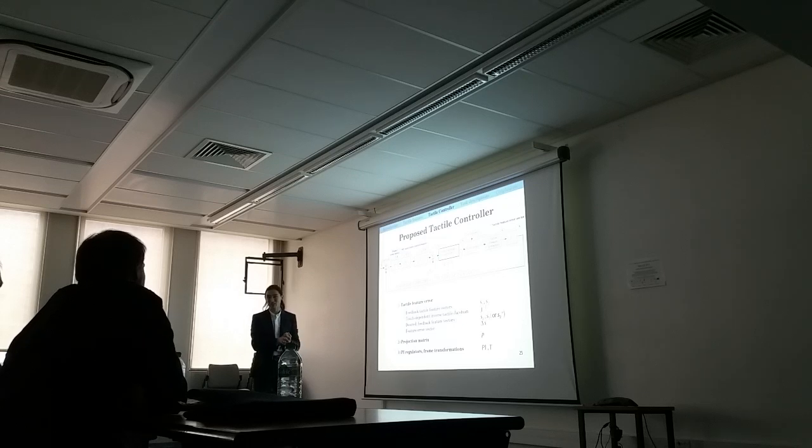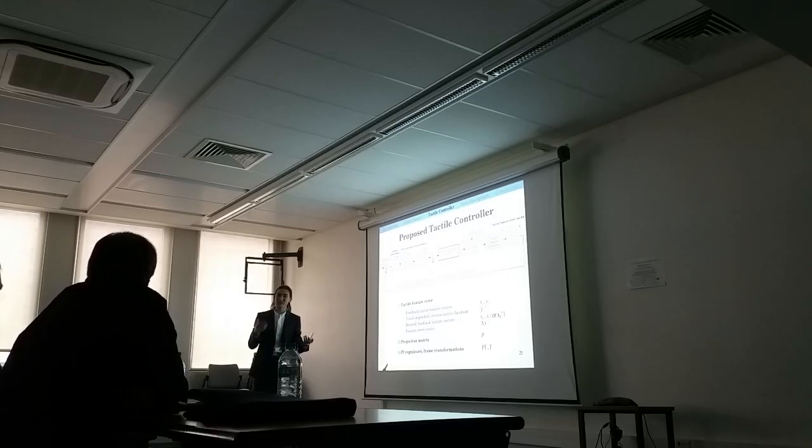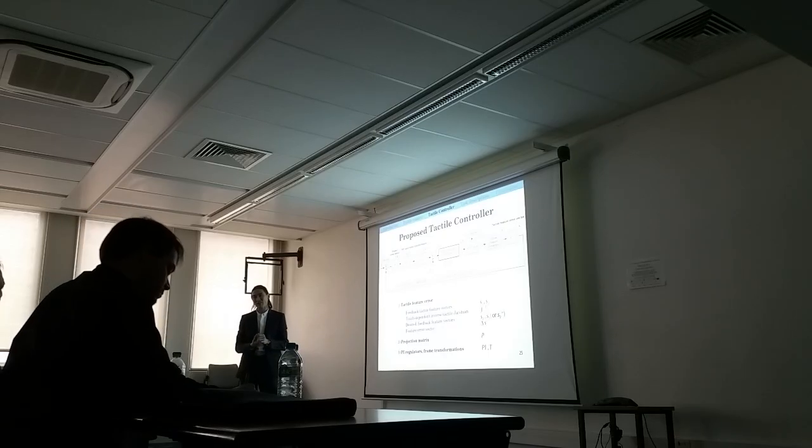It's known in advance here. It is changed online, as soon as the edge contact is detected, and then it starts sliding. Okay. So we can actually program in advance, hard code these exploratory movements: come to contact, align, and move. So it's hard coded in advance.